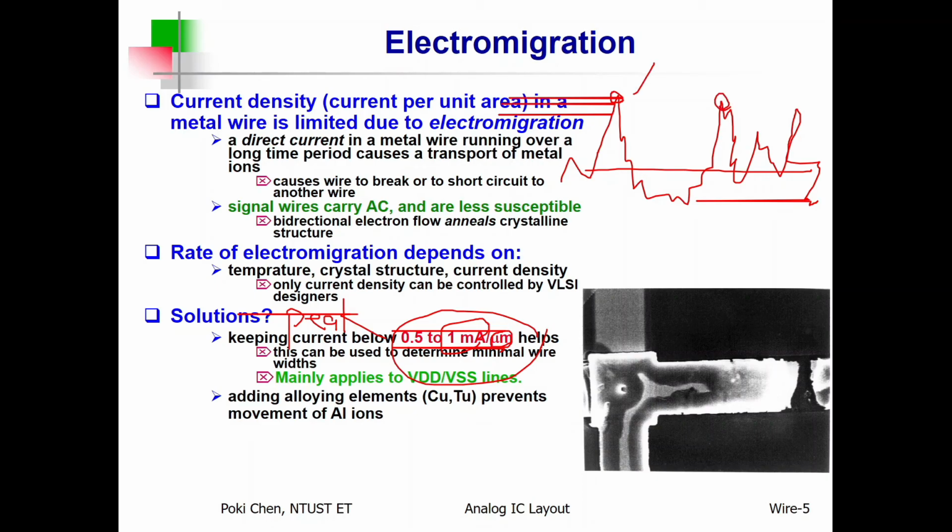So after you get the peak value here, for example, it is 5 milliamperes. So what does it mean? To play safe, the width of the metal line should be 5 micron. Okay, that is what I recommend.